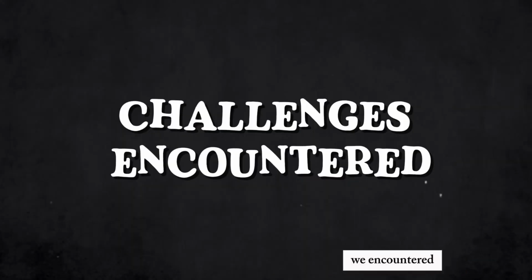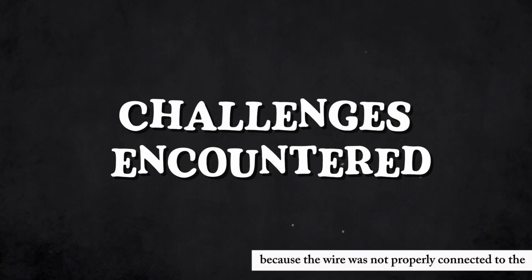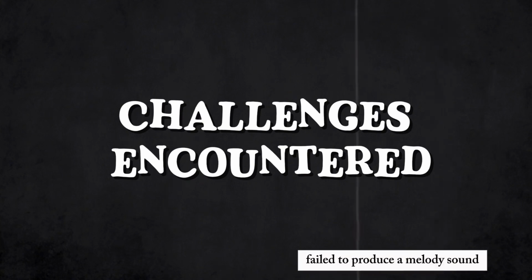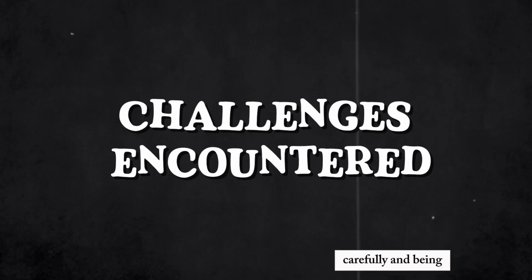Throughout the lesson, we encountered only a few challenges while completing the activities. In Activity 2, the button did not work at first because the wire was not properly connected to the button's leg. And in Activity 3, the buzzer failed to produce a melody sound during our first two attempts. These challenges taught us the importance of checking connections carefully and being patient in troubleshooting until everything functioned correctly.